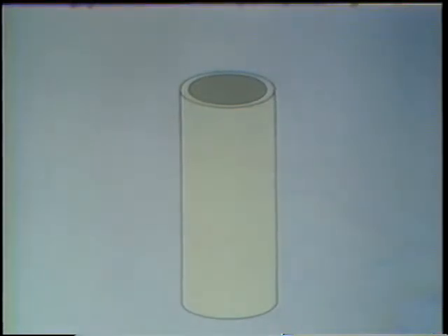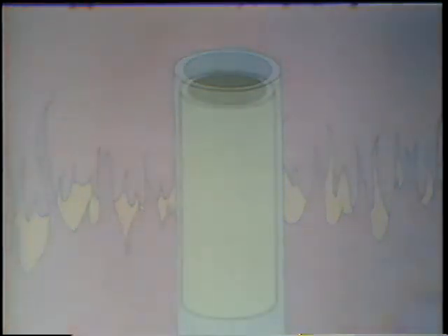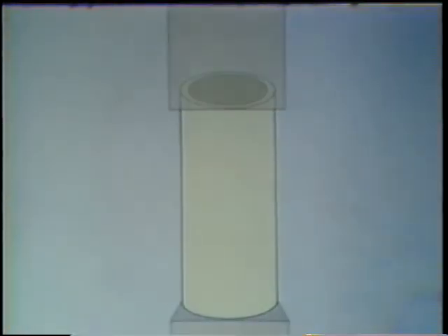Thermal expansion is another cause of mechanical stress. Expansion takes place whenever the boiler is fired. The metal tubes expand when they're heated and contract each time they're cooled. If this expansion and contraction can't take place freely, mechanical stress is created.